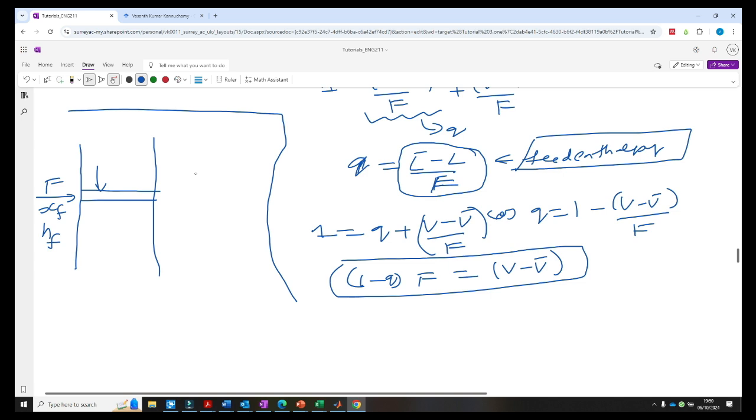Yeah. And if you heat the vapor to something like a superheated vapor, then the superheated vapor contains more amount of heat. So then obviously the enthalpy of the superheated vapor will be much higher when you compare it to the liquid or when you compare it to the saturated vapor. Okay, sorry, saturated vapor. So let's come back to this topic.